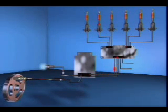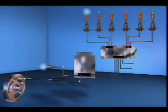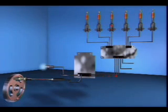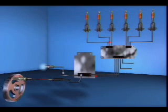The ECM commands multiple or single spark discharge by varying the length of the spark reference signal to the ICM. Multiple spark discharge at low speed or power conditions results in better spark plug life and less chance for engine misfire.